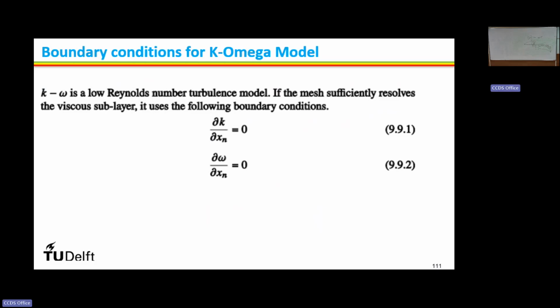Okay, so this is the wall, right? This is the solid surface. If the wall is not there, what will happen? There will be only uniform flow. For uniform flow, there is zero shear. There is no shear, the gradient must vanish. Who is providing the shear? Well, so what is this model doing? K epsilon away from the wall, K omega at the wall. While blending, based upon the shear stress, information is transmitted from the wall to the region. So that's why they name it shear stress transport.